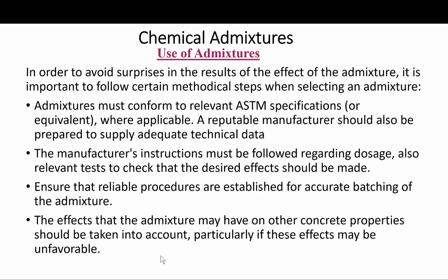Exactly, because any variation, any change will introduce a whole new set of variables. So be careful. You must replicate the same job conditions and use the same materials in order to predict the effect of that admixture exactly.